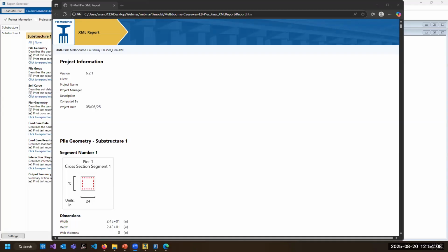So considering the bearings, we would just model half of the bearings in the model, and when we use the wind load generator, it seems to assume it's a whole bridge, but actually we only model half of the bridge. So I think the wind calculation is off a little bit. We want to know how we adjust the wind load input to truly reflect that only half of the bridge was modeled, not the whole bridge.